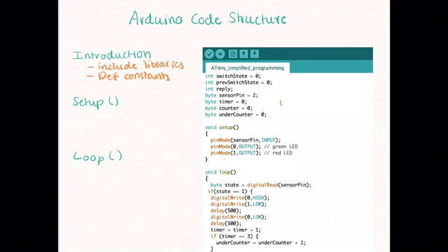different from the introduction up here, but the main difference, as you can see, are these statements called pin modes, and I'm going to write this down because it's unique to this setup. So what pin modes do, they allow you to declare certain pins as inputs or outputs, and this is usually done within the void setup. The setup, as you can see, runs only one time, and it runs after each power-up or reset of the Arduino board. If you don't understand why that is, it's because everything declared in the void setup doesn't change.